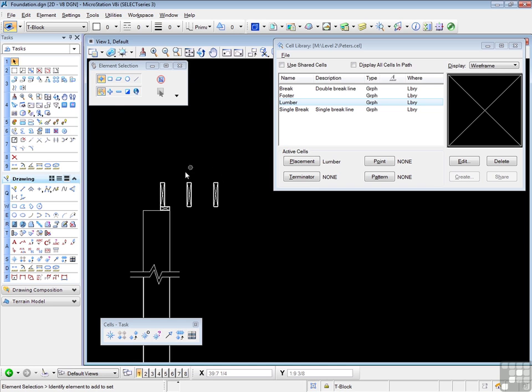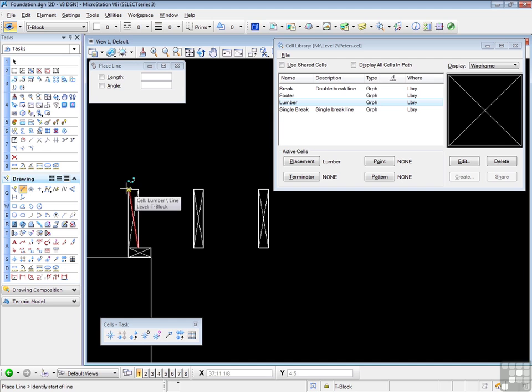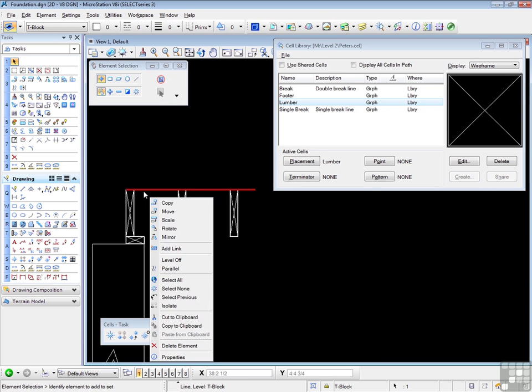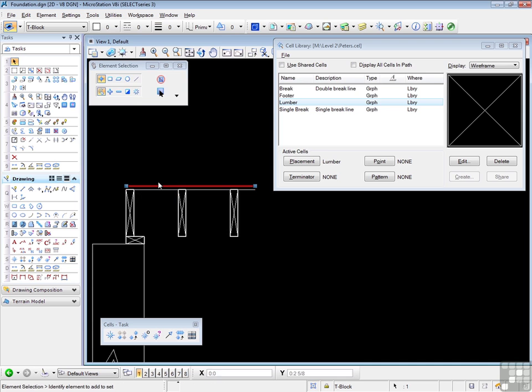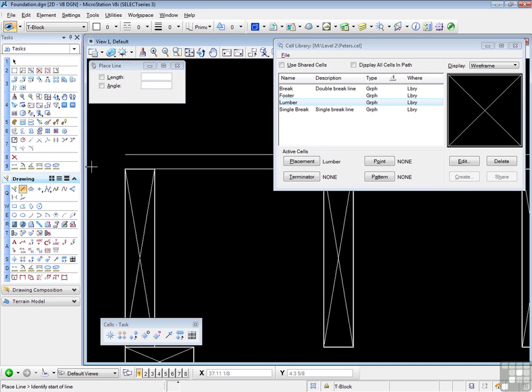So far, so good. Now I need the 3/4 inch plywood. Back to the line drawing. So the first line will be there, running across to approximately there. I'm going to copy that up by 3/4 in that direction by 3/4 of an inch. That's going to be :0.75. That's my 3/4.